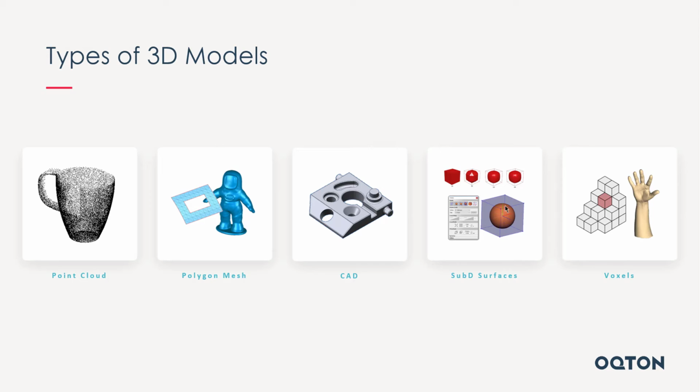Now, two other ones that I'll cover really fast. Subdivisional surfaces. These are a surface type that's used a lot in animation and the AR/VR world. Different types of representation in the world. What these are very good at is push-pull modeling. Subdivisional surface models is what you'll hear them called. They're kind of like a hybrid in a way. I think of them as having a NURBS surface that's controlled by a polygon outer armature or frame that helps pull and push and create shapes. Again, used in AR, VR, and animation.